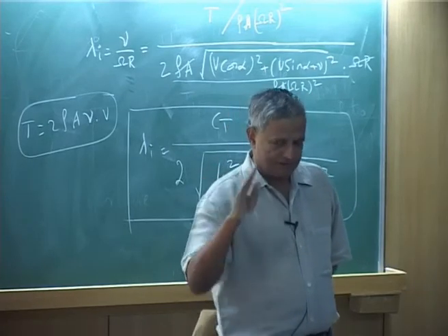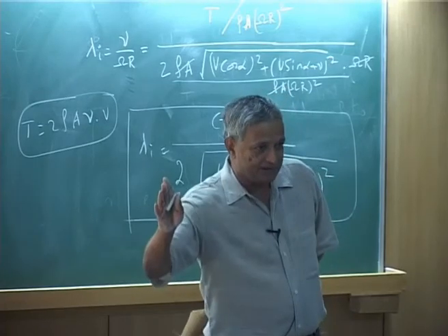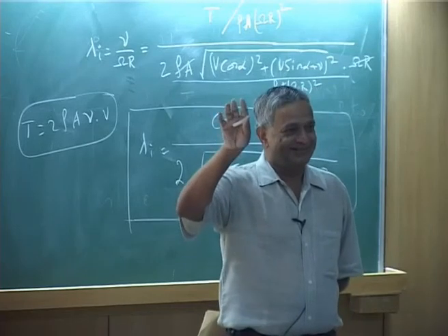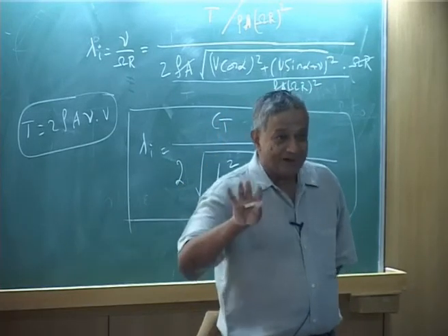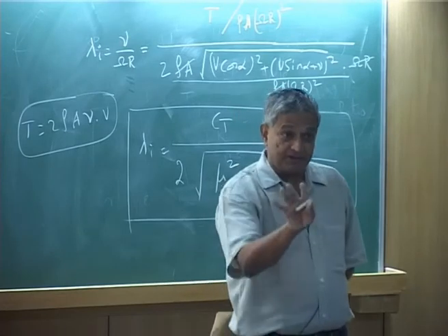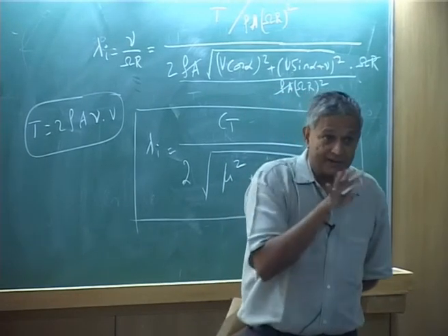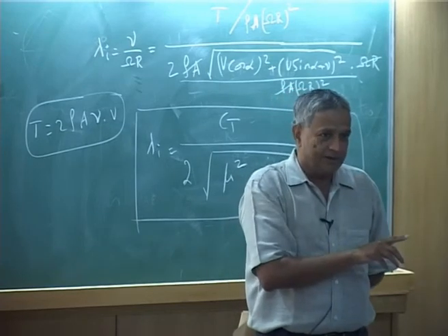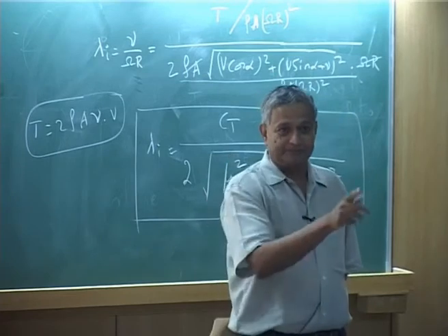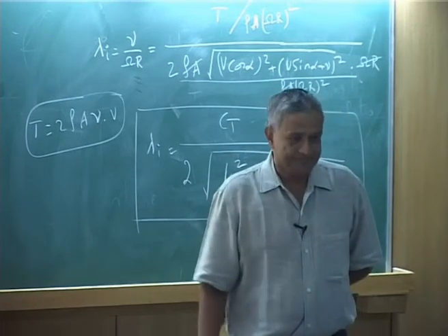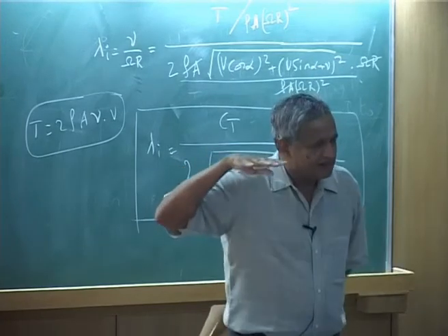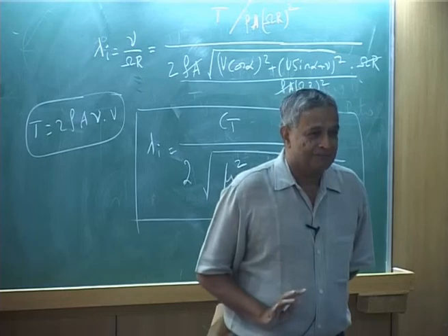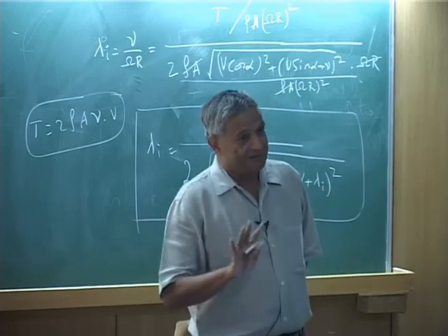You will find that whatever aerodynamic model you use, as you go to high speed, they all come close. Now, I will answer your question later. You may use different models in gross estimates, but not in loads. Vibratory loads vary with what theory you use. When it is flying in equilibrium or trim condition, you will find it does not matter. That is the beautiful result.